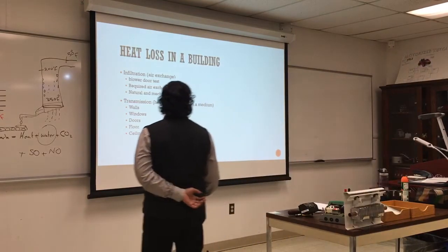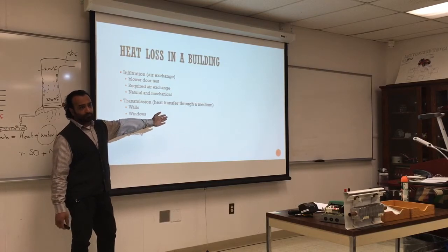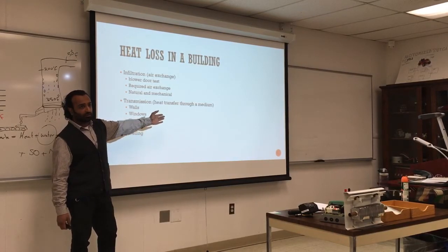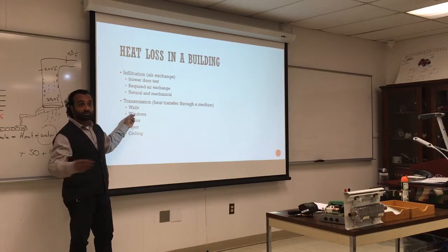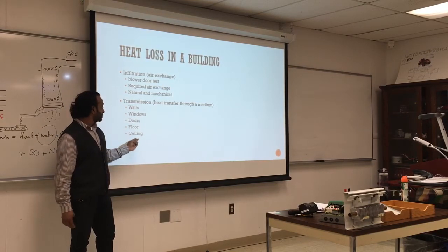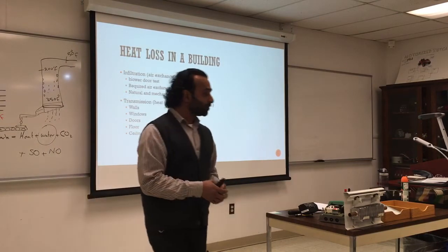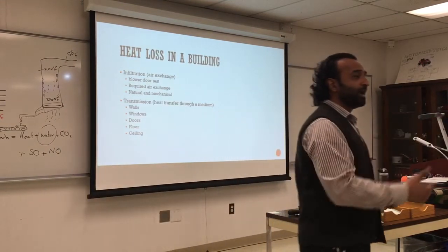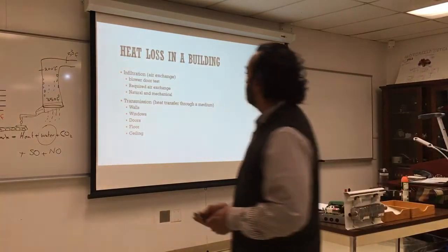Transmission is heat transfer through a medium. That's what we do the calculation on. Walls, windows, closed windows because it's solid, doors, floors, and ceiling. This is all transmission through a medium, through a wall. Just because we have a solid wall does not mean it does not conduct heat.